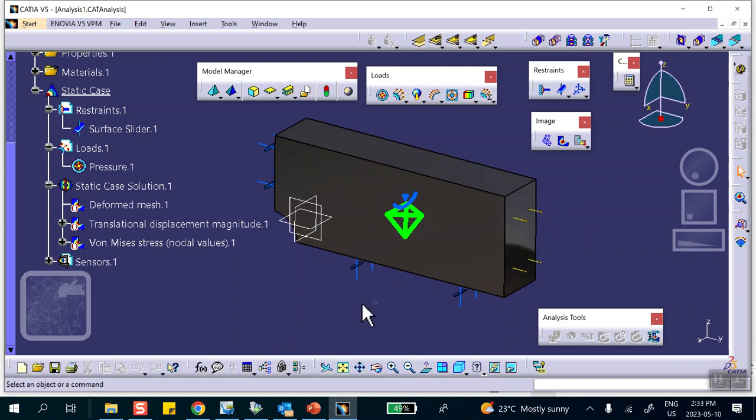Now, make the element smaller in the places of maximum stress. It's not really actually the maximum stress, it is where the variation of stress is very rapid. If you look at the color distribution, it was very compressed here. That means this is where the place of action is. So make elements smaller here, run it again, compare.